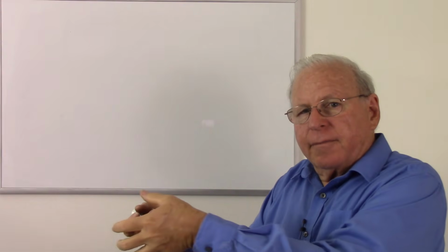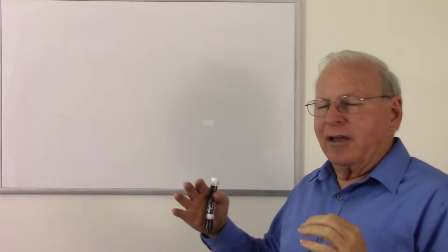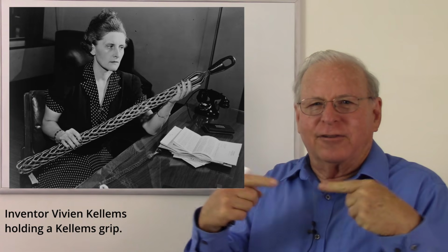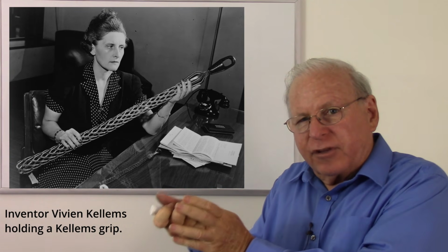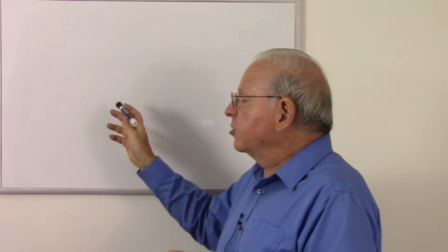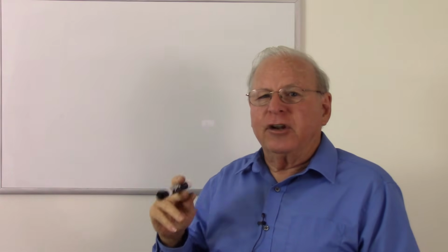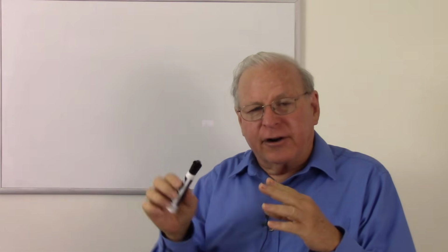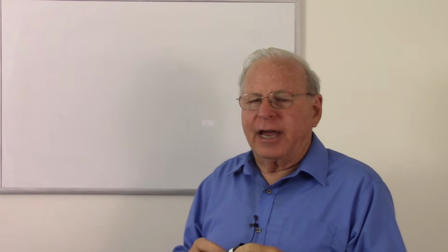We also want to be able to pull the jacket along with it, but we want our main pull to be on the Kevlar itself. We have this thing called a Kellems grip, which is basically a wire version of those little Chinese finger things. You stick your fingers in, you can't get them out, and they put that to hold onto the jacket, but then the main pulling is actually pulling on the strength member of the fiber. And when you're pulling it, you don't want to pull around sharp corners. The rule of thumb is do not pull it around a corner that's any tighter than 20 times the diameter of the cable. Once the cable's installed, then you can have tighter turns. Once it's installed, you want bend radii no less than 10 times the diameter of the cable.